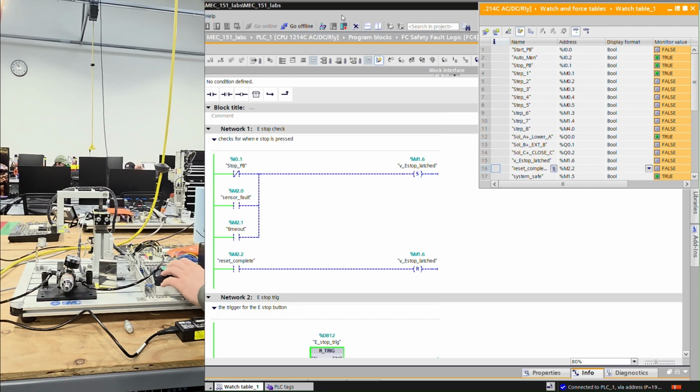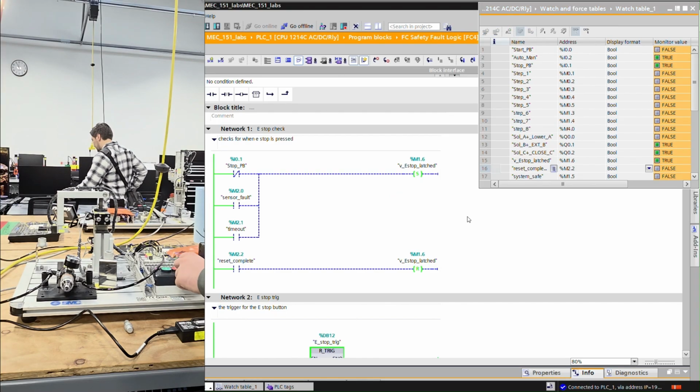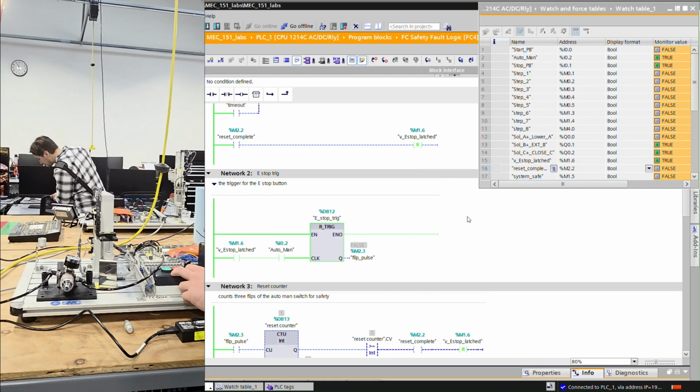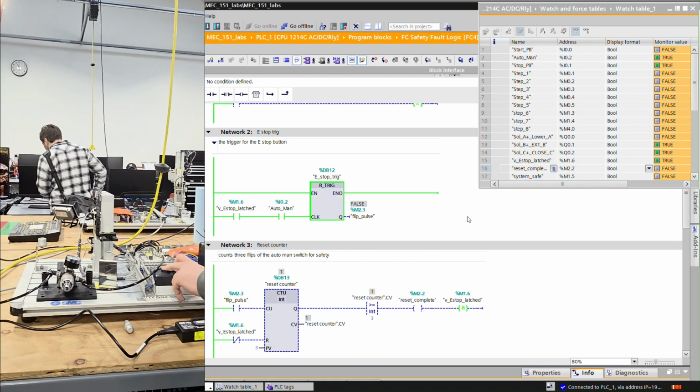Now let's observe the physical system override path during a live execution. When the station is cycling automatically and the hardware stop button is depressed, an immediate master memory purge is initialized. The logic instantly clears the sequence bit footprint from step 1 through step 8, terminating all automated looping parameters.